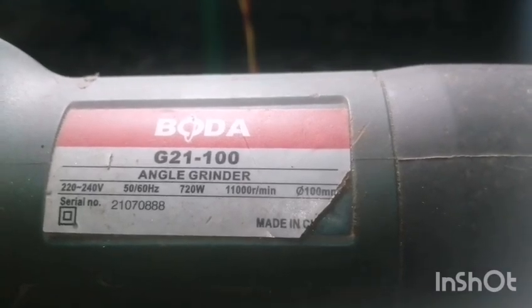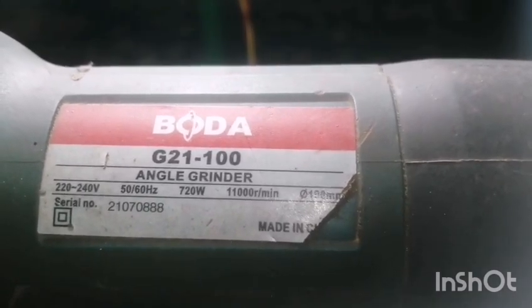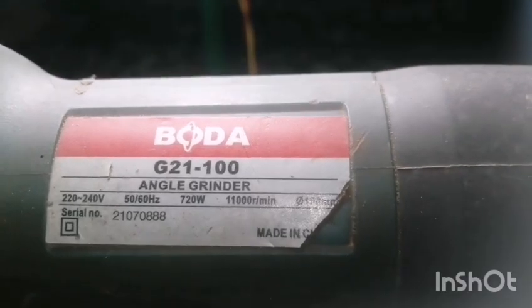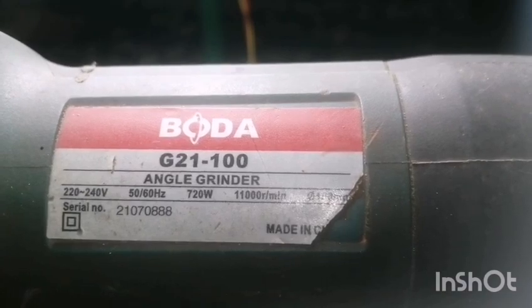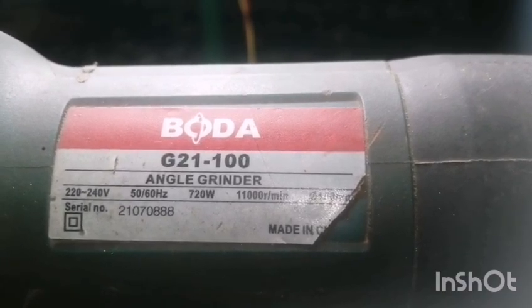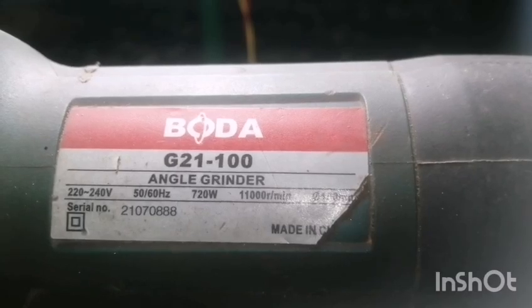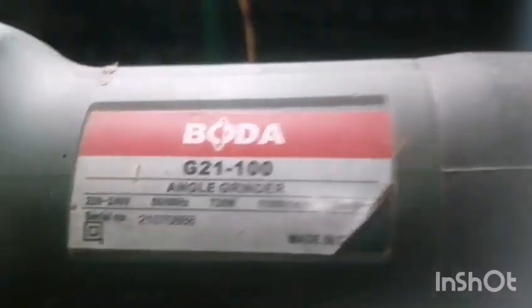This is its nameplate, and you should always connect it to a 220 line, not 110 or 440. Otherwise, it will burn out.